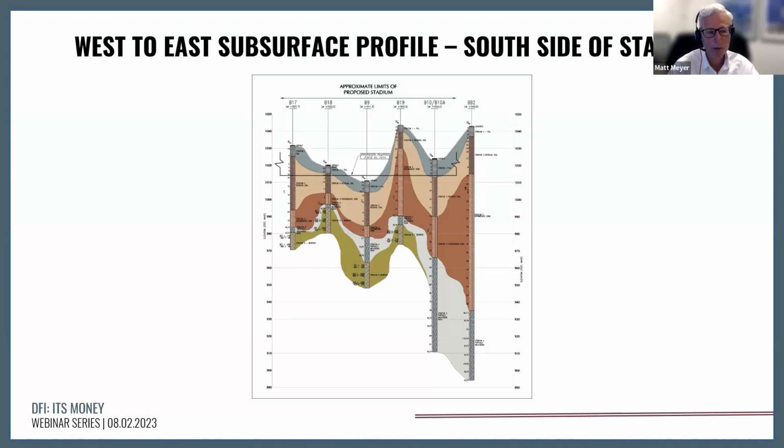However, for the purposes of this variable length system and delineating an intermediate geomaterial for frictional resistance, we backed that criteria off a little bit to make use of that greater thickness of that layer compared to the 100 blow criteria. Below the sky blue layer is a green depicted strata, that is the bedrock. The bedrock at this site is amphibolite and biotite gneiss, mostly biotite gneiss with some amphibolite zones in various areas of the project site.